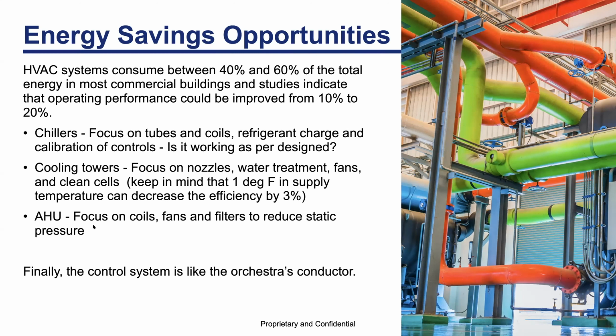Surge prevention algorithms are critical to make sure that the compressor operates near the surge line to maximize its efficiency. This is valid for both constant speed and variable speed, but it's extremely important on variable speed chillers or compressors, which nowadays are very common. The question always must be how far my equipment and my system are operating from design.